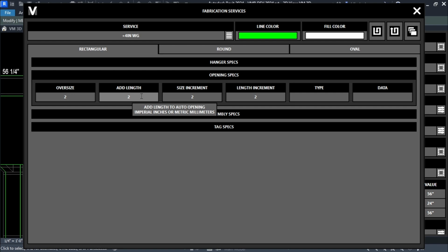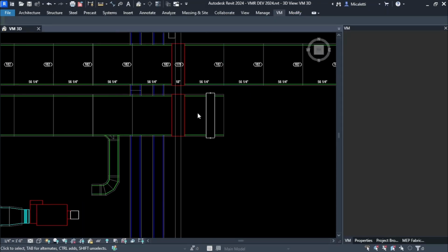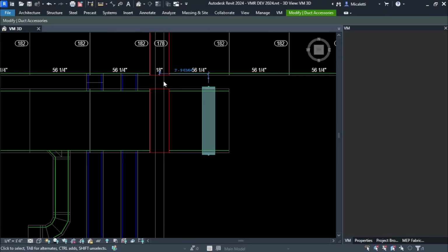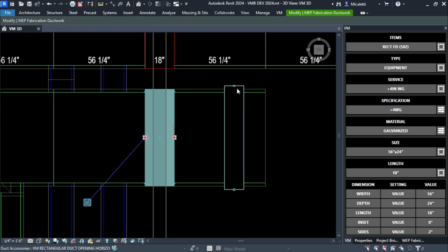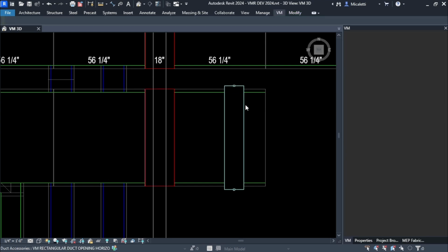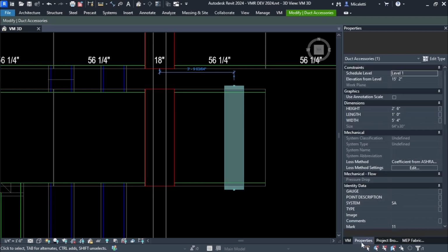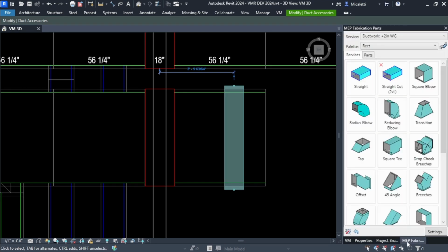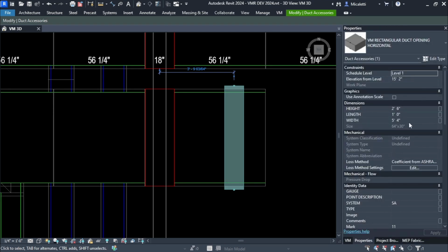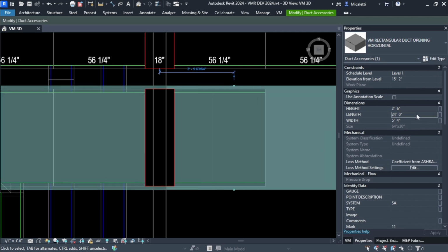And length, it should probably say something about the wall. It doesn't. But here's another good thing: I made this a manual sleeve, so it didn't have a wall to pull the length from. It did control the size, but manual sleeves are still responsible for the length. Be aware of that. Here, change that. Not 24 feet.